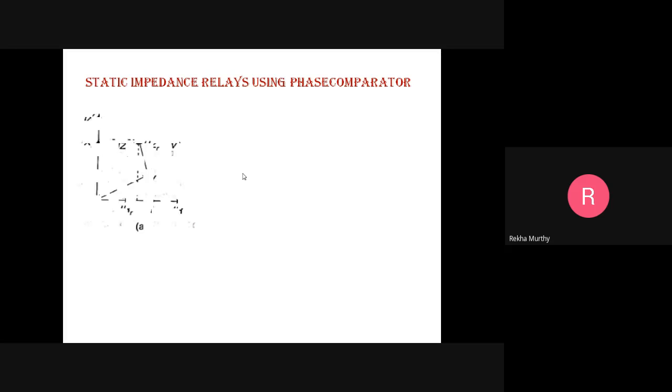Now let me consider this phasor diagram, wherein we are going to consider the current as a reference, and the product, when you multiply this with the R, is IR. This will be the IR drop, which will be in phase with the current I, as we all know, and I into X always leads the current by an angle of 90 degrees.